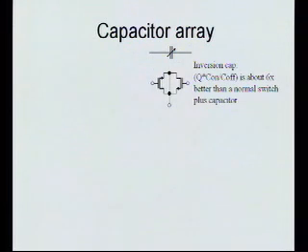So I used one of several different kinds of switchable capacitors. In this case, I used what I'm calling an inversion cap, which basically makes use of the fact that if you take a typical FET and you switch it between strong inversion and strong depletion, avoiding accumulation mode, then the capacitance changes dramatically, because in depletion mode, the gate capacitance is basically either to the source and drain or all the way down to some really deep depletion region.